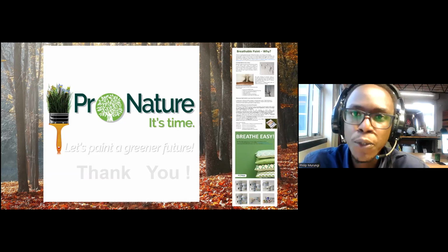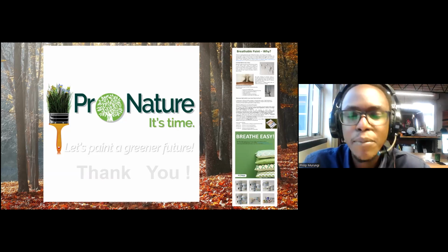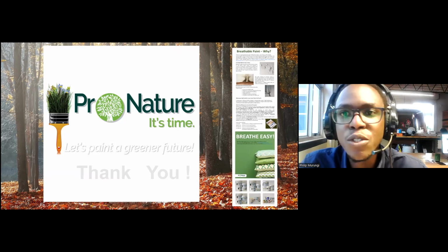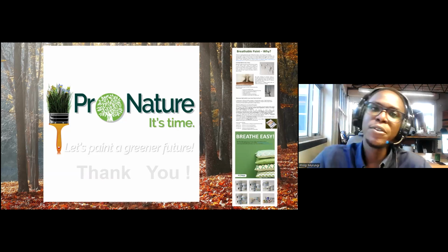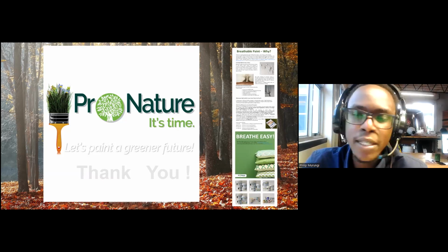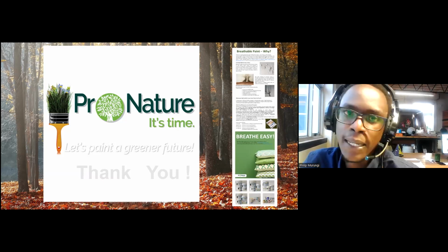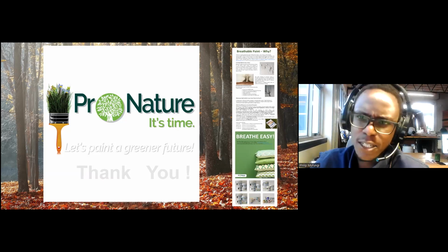But yeah, if you put paint on that brick, you will get problems that you will see, because the difference in the absorption rates is so high. Whereas the difference in absorption rates between lime and brick is not high enough for you to see problems like that. I hope that answers your question.